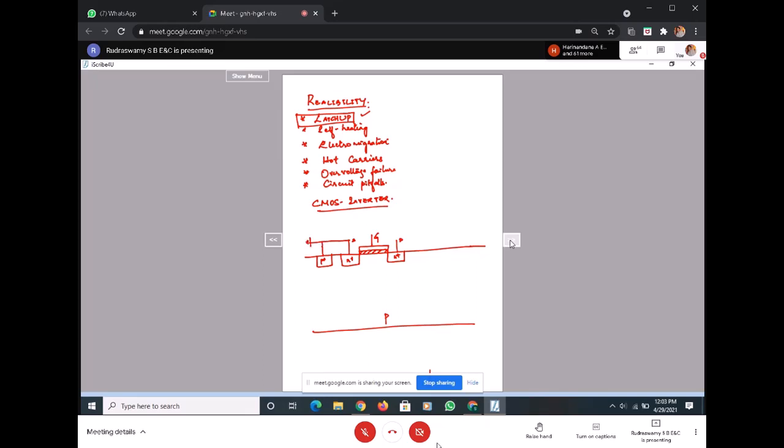We know that, right? If I want a CMOS inverter, it will have both NMOS and PMOS. I can construct the NMOS directly, but in order to have a PMOS, I need a well, and that is what this well is all about. Then I will have the P plus diffusion, and then the body is my N plus.